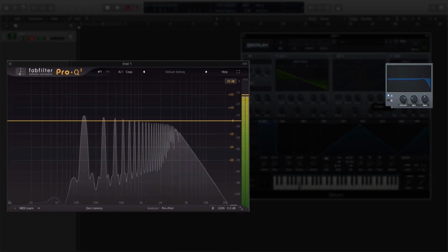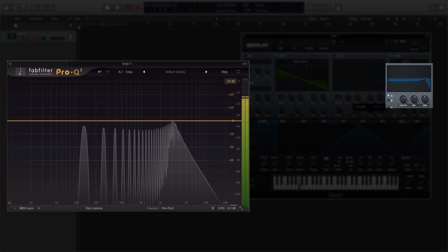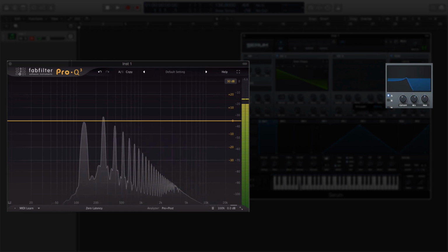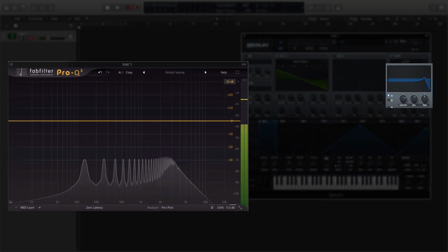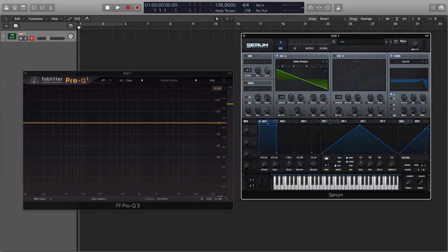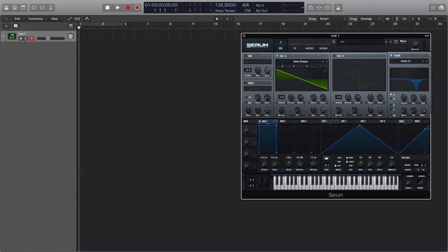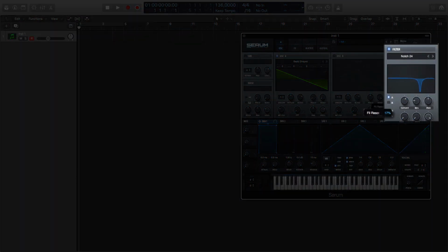The resonance is the accentuation or boost of the frequencies at the cutoff point. It serves really well the purpose of emphasizing what the filter is doing, particularly when we have it modulated up and down, and it can also be the width of the band reject filter band.